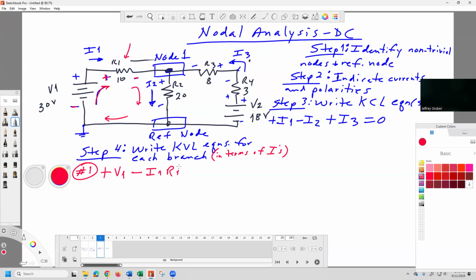There's current going through this piece of wire that has some resistance, so it's dropping some voltage across there, and it's dissipating power, because there's current and there's voltage. That's an IR drop. Kind of a feedback loop. Once it gets hot, the resistance goes up and then it gets hotter. It's a positive feedback loop.